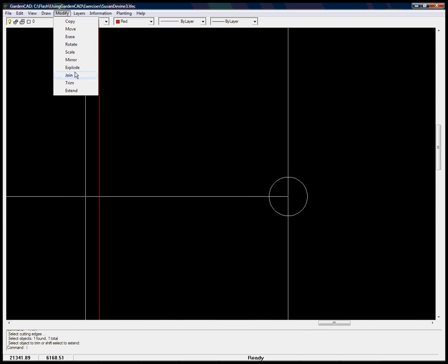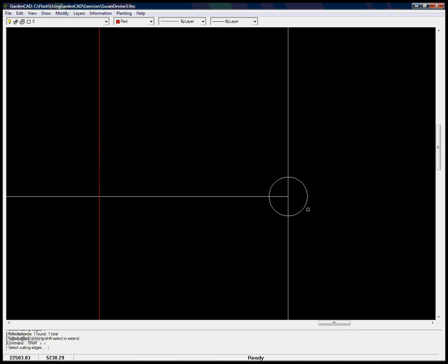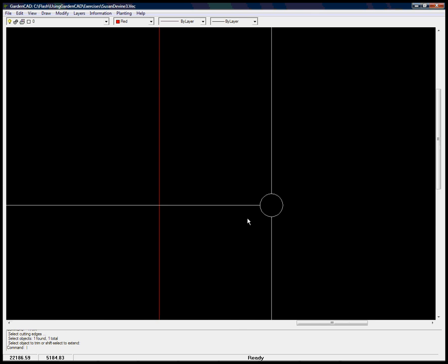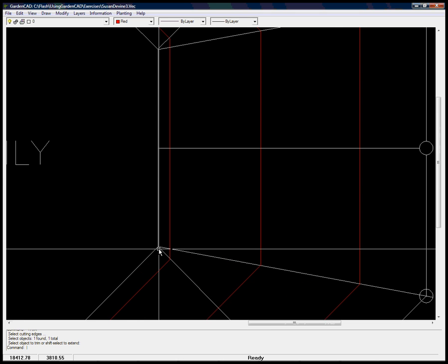We'll do the same down in here. So it's Modify Trim, but you don't have to do it that way. You can simply right click and repeat the trim. It remembers the last command with the right click. So we click there and knock off those lines that are through there. There was a double line through there because we're at that midpoint where we mirrored things.